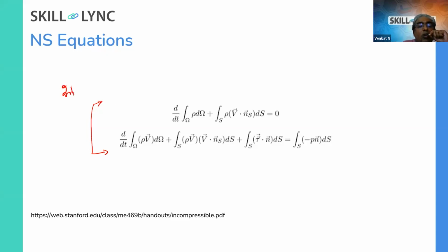So you can see there are so many forms, and these are generally, as some of you have told, coming from the Reynolds transport theorem. That's great. And these are the equations. These type of equations are actually being used in the finite volume methods. Control volume for fluids, at least the finite volume method is very popular and convenient also. So they use this integral form of approach for your CFD, solving the Navier-Stokes equations in CFD.